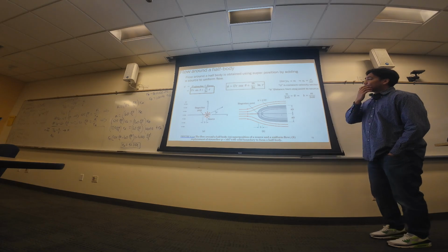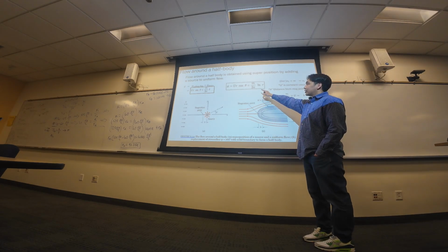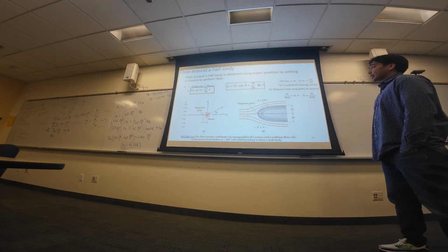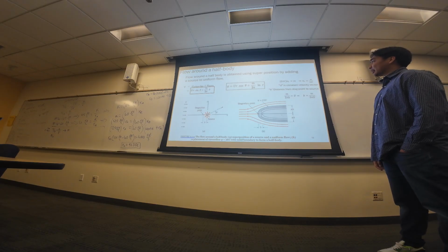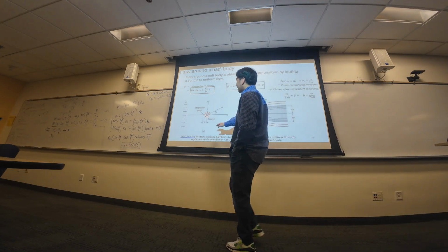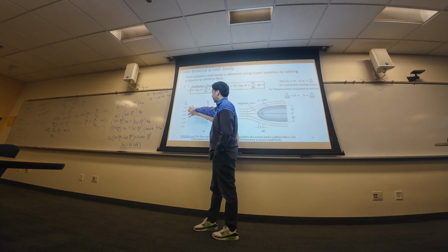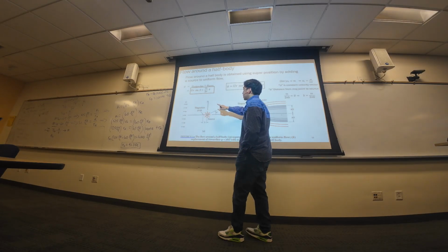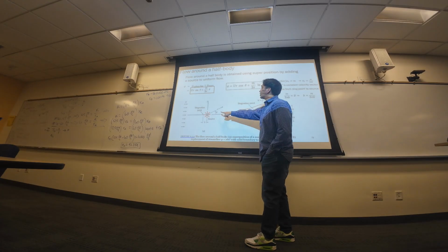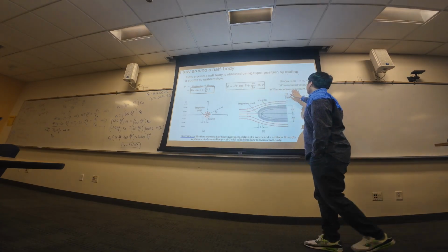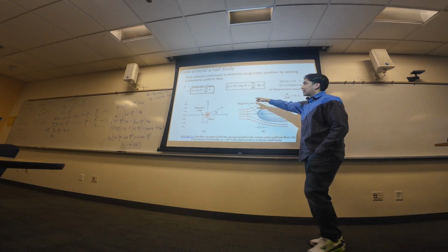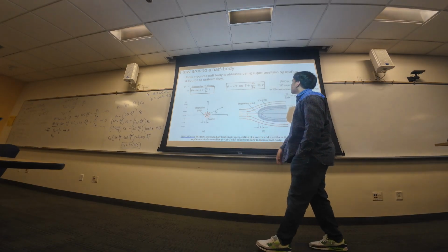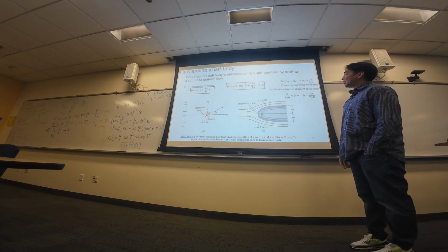And then here's our equation for phi, which is your velocity potential. And like I said, I hate having just an equation on here where you don't know what every variable means. So, summary: U is your flow of vectors that are constantly approaching. r is the radius here. m comes from over here, right? This is your flow value. Theta is angle. And that should be all the variables.